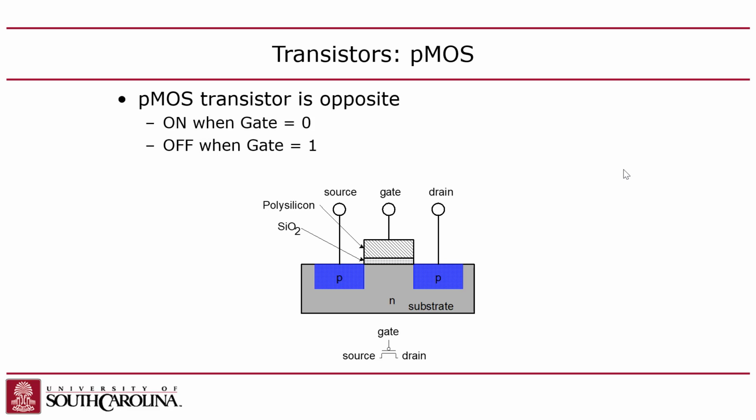Now you might say, wait, hold on. What about the diode effect though? How do you prevent the diffusion areas from dumping all their current into the substrate, or vice versa, the substrate dumping current into the diffusion areas? How do you guarantee that these are not electrically connected? Well, you have to bring the N, in this case, this has to go to VDD. So the substrate on a PMOS, you have to energize the substrate to VDD. That way, you have the voltage of the substrate higher than the diffusion areas to reverse bias those diffusion area diodes, right?